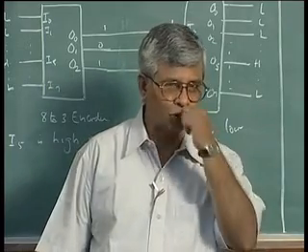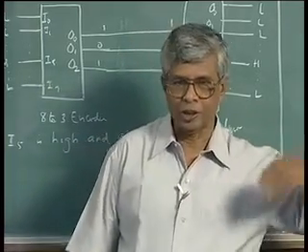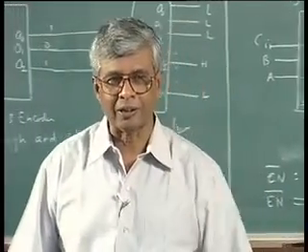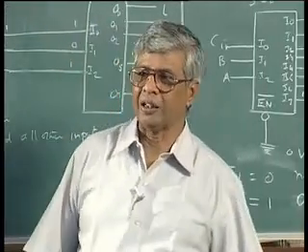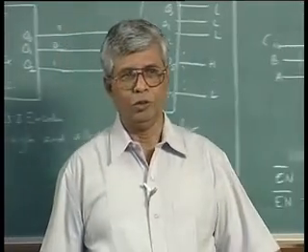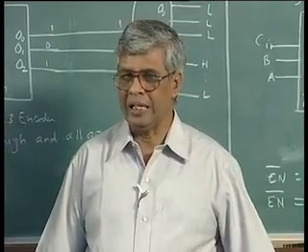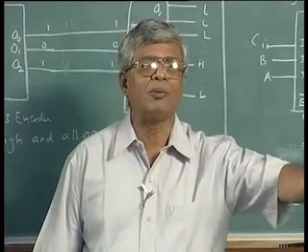Practical reasons, of course. Mathematicians may argue that it's not 0, it's not open, but we are engineers, not mathematicians. So we have to be practical. When you do something, you have to tell the practical implications. So high impedance means the output is as if it is disconnected from the rest of the circuit.